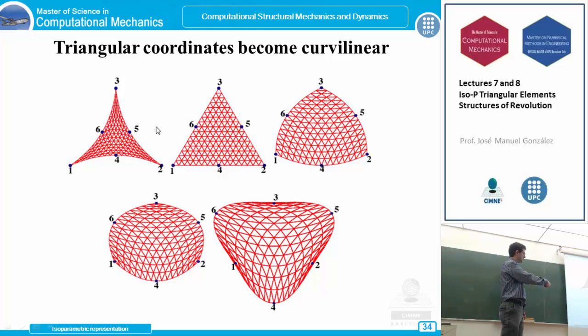as convex or not convex curved sides, and we can even work with this triangle, where, imagine here we have a curved side. This curved side is easily represented by these 3 nodes. So these 3 nodes represent this curved side in the geometry. Here we have as well these 3 nodes to represent a straight side. So these 3 nodes are able to interpolate a curved side and a curved displacement function.